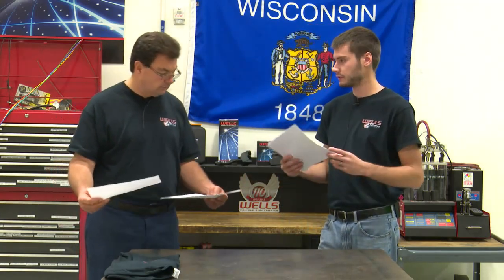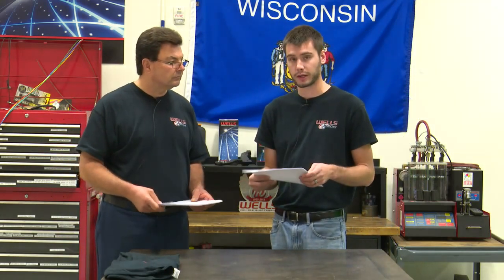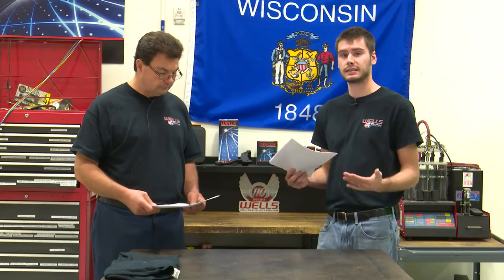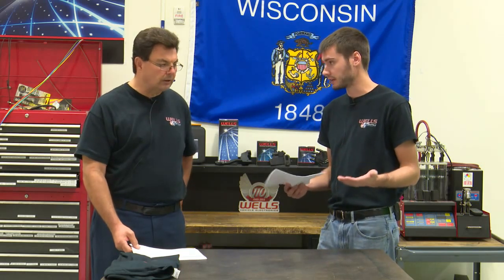So lowest number, right. Okay, so out of our codes so far, you'd start with the P0101. But that's really interesting in the fact that the conditions for running this 121 code, you can't have that 107 set. It makes sense. It needs to see the MAP sensor functioning normal in order to test the TP.